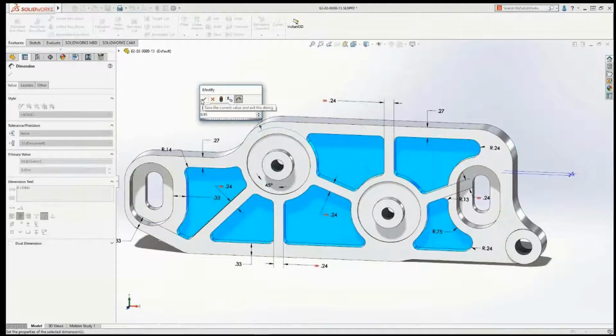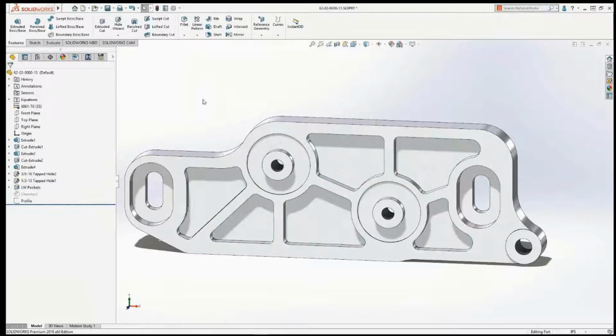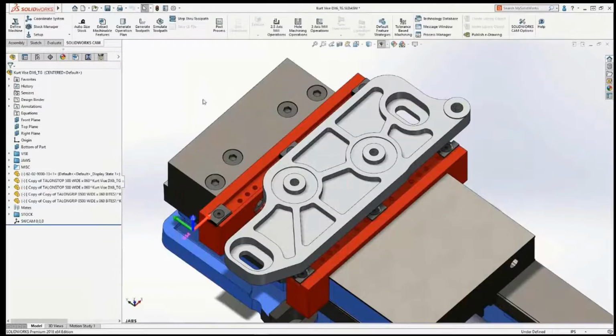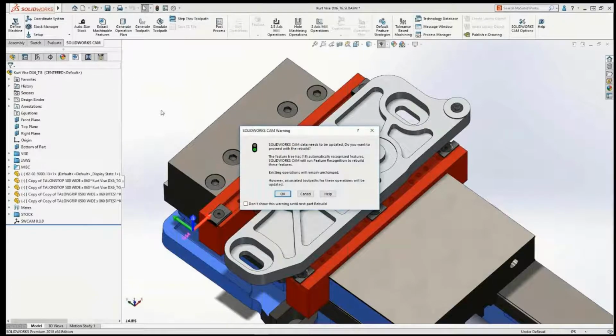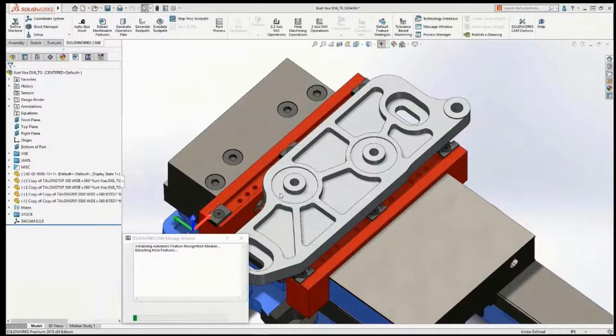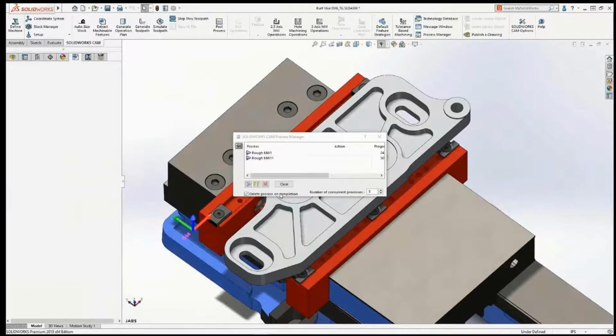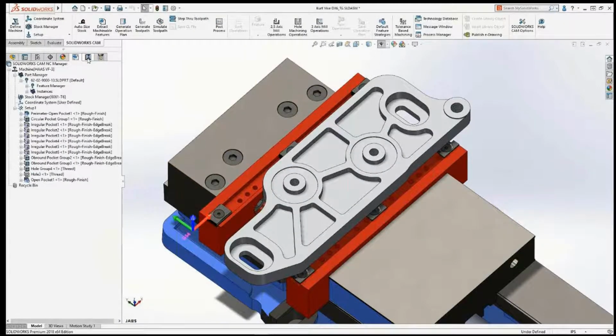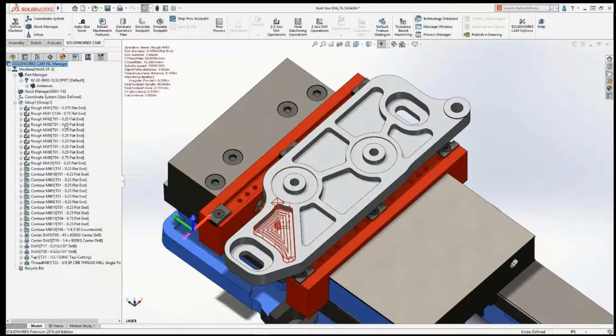And then after the CAD modification, return to the assembly environment. When you activate the CAM tab, you will find a message saying that some CAD modification happened, and asking if you would like to update the toolpath according to your CAD modification or not. If you say yes, then the whole project, the whole programming, will be rewritten according to the new modification, which means you didn't do anything to your project. It's only one click, and that click changes all your programming lines.